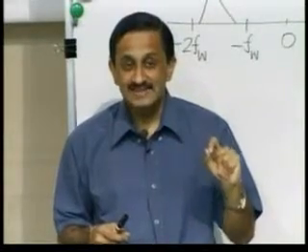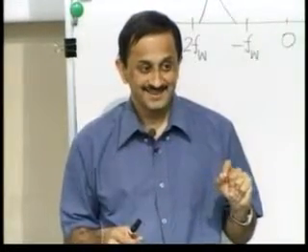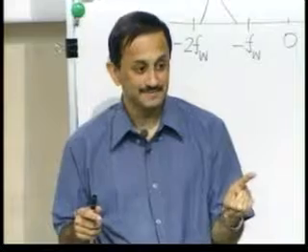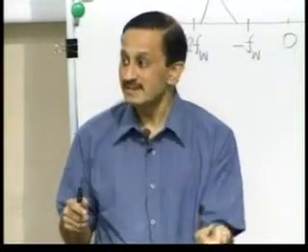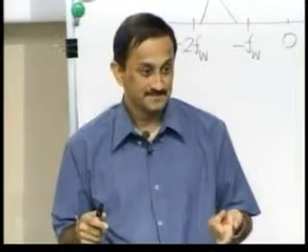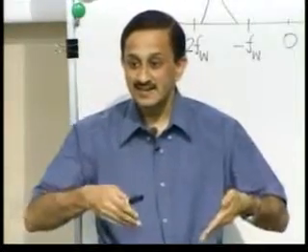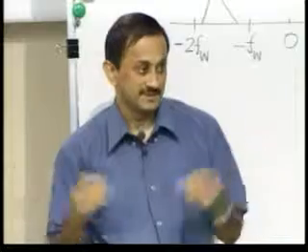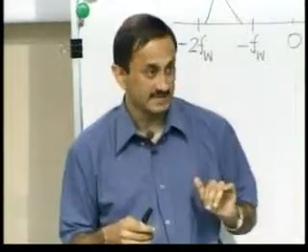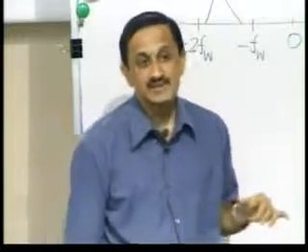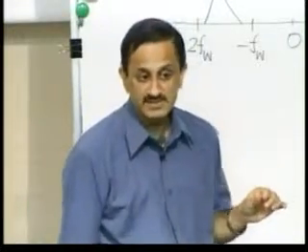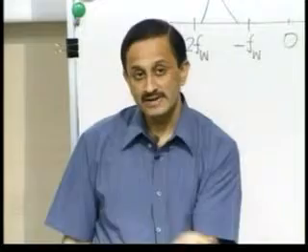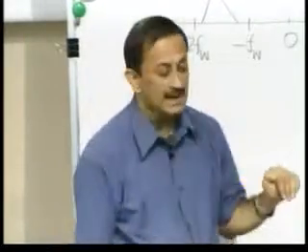Now, as I said, this is deceptive. This is deceptive because every sample that you take is a complex number. So, actually you have 2 real numbers being taken at every sampling point. So, all that you are doing is, initially you were taking 1 real number at twice the rate, here you are taking 2 real numbers at half the rate. Right. So, there is really no advantage in that sense, right. Of course, this is just a little aside that I have mentioned. However, this fact can be exploited in some situations, right. One can, if it is convenient to store 2 real numbers at a time, one can actually make use of what is called a complex envelope to a signal and sample it on that basis.